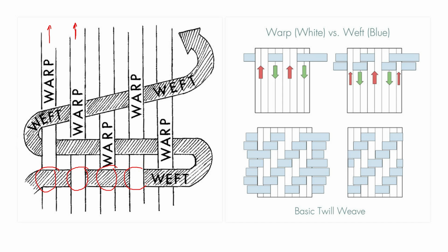In these places the yarns are interlacing, and this interlacing pattern here is one up, one down, one up, one down. Like that here, if we consider one line, its interlacing pattern is one up, two down, two up, two down, one up, like that.